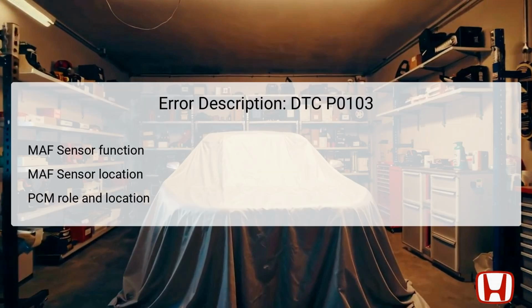The MAF sensor, or Mass Airflow Sensor, is responsible for measuring the volume and density of the air entering the engine. This data is crucial for the Powertrain Control Module, PCM, to make necessary adjustments to the air-fuel mixture.